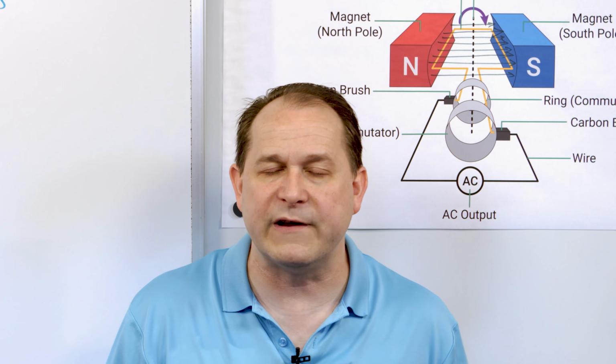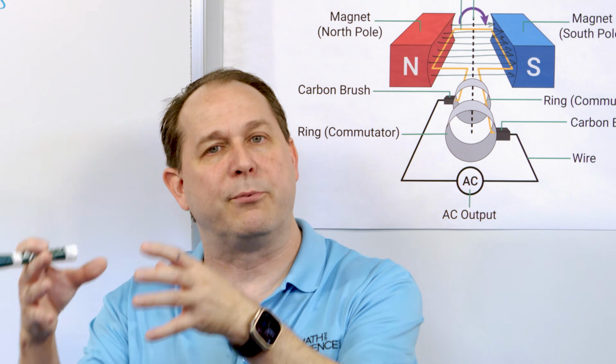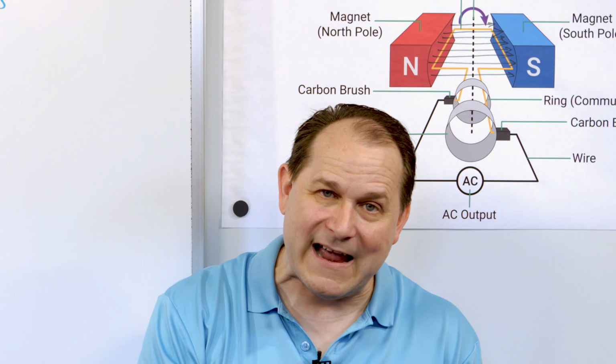And because it's a sinusoid, we can use transformers to step the voltage up and down, because transformers, the same way this induction only works with something changing over time, need AC electricity in order to step the voltage up or down. All right, and that is why we have AC electricity so prominently in our houses, because we can generate it very easily using a system like this. We can step it up and step it down and transmit it over long distances without too many losses. And you just have to be careful, because you have to step it down. Otherwise, it's a dangerous voltage that could kill people and things like this.